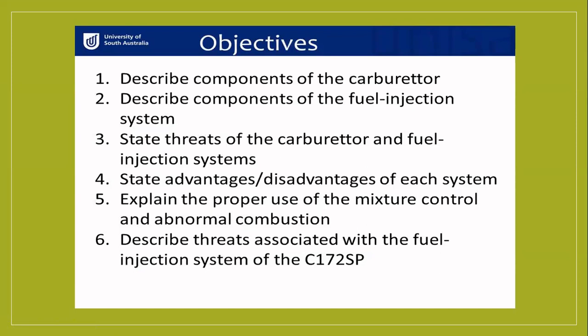They will ask you clearly. For SI engine you will write carburetor and other accessories. Carburetor alone is not enough. The fuel tank, the filter, on-off valve with casing, pipes, fuel pump, then carburetor, then inlet manifold, like that. That is called fuel injection system.